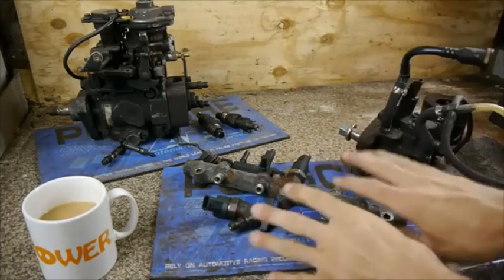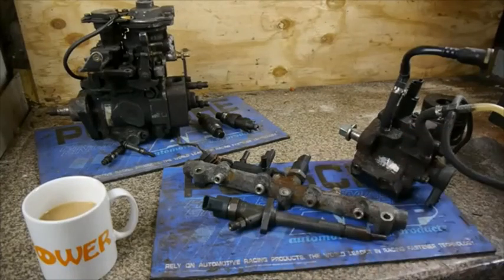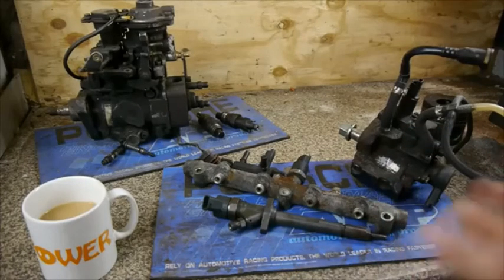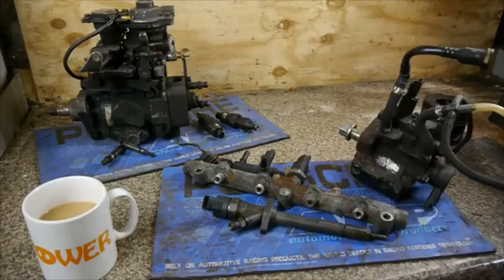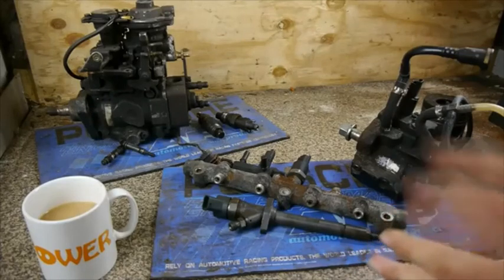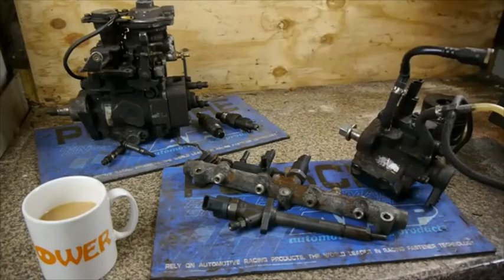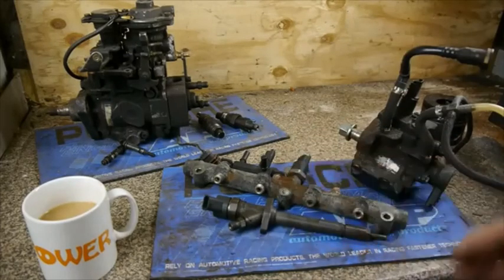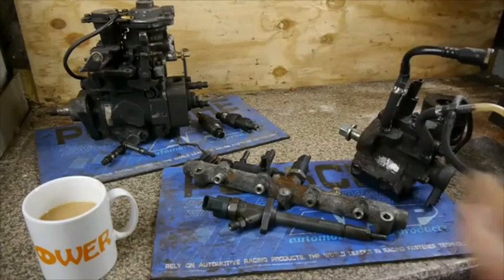However, is this system better? Well, yes. It's more modern. And whilst with a lot of modern things we like the nostalgia of the old things, it is superior. It creates higher fuel pressures, which enable you to run more power without stresses and strains on springs and levers. And there's more flexibility with the tuning process. So you can fire more fuel in this system in a shorter period of time, which is obviously better for combustion and atomization of the fuel.